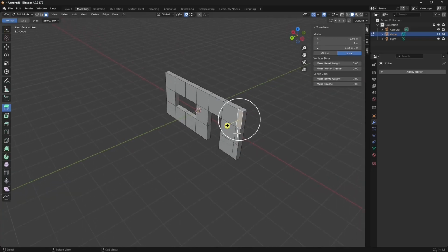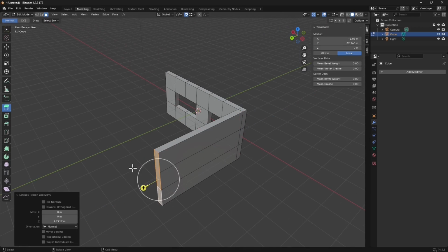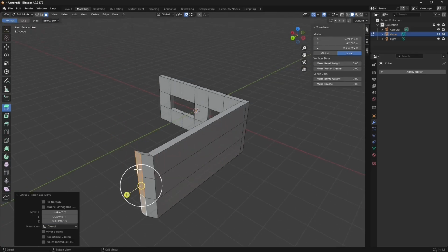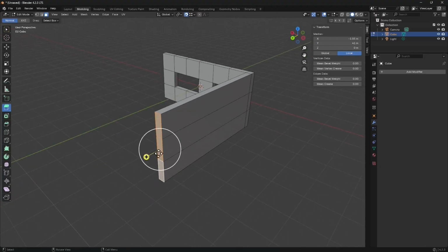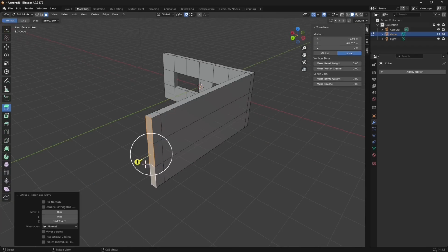And then I'm going to go from this other side and click and drag again. And let's do this like 6 meters. So I'm going to type 6 or 5 or 4, whatever you want to do. And then again, be careful here when you extrude. Don't be in the white circle, but you need to carefully select the yellow gizmo there with the plus icon. And again, I'm going to do this 0.3, so it means 30 centimeters.